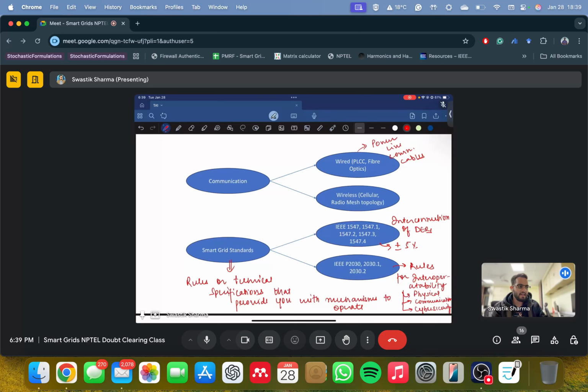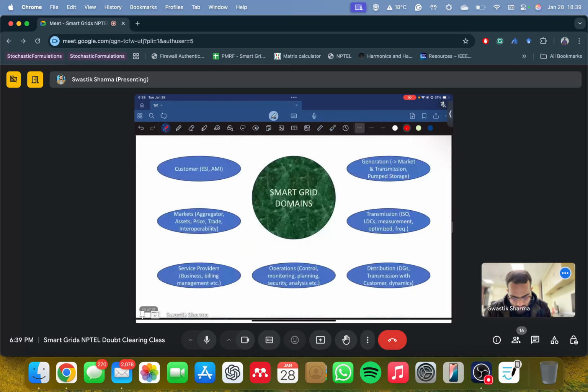Let's say you have connected a solar PV power plant, and it's very varying in nature, and you have not connected anything to smoothen out its output. So you're causing voltage fluctuation. It tells you that it should not be greater than plus minus 5%. These are some rules that they tell. If you want to know in extensive manner, you should read the class notes. Class notes are different, this lecture is different.